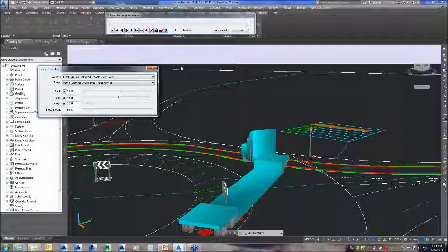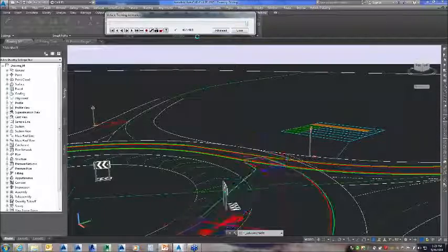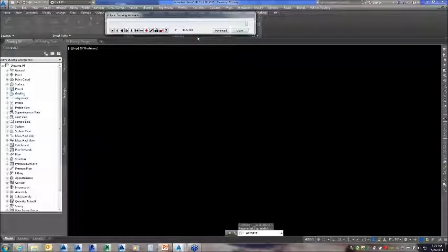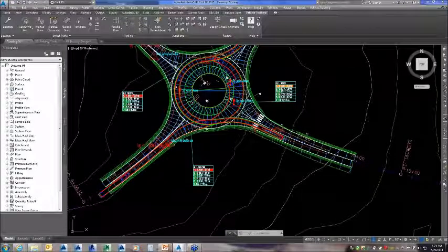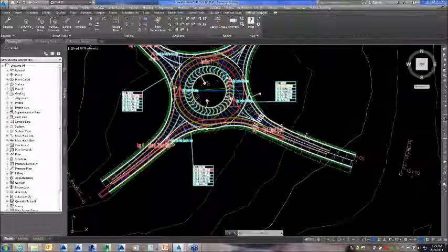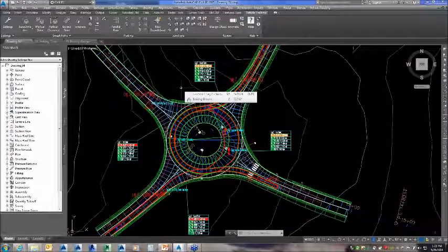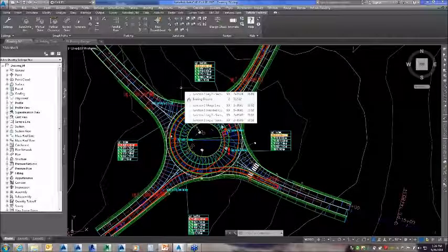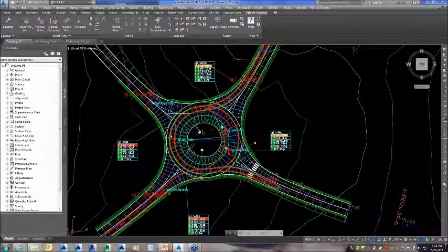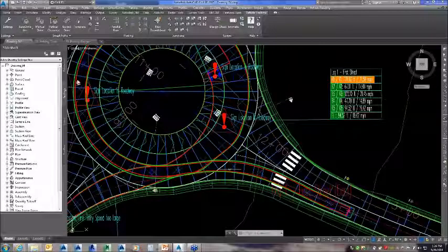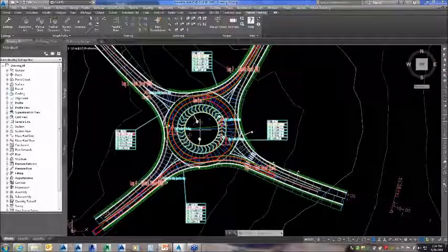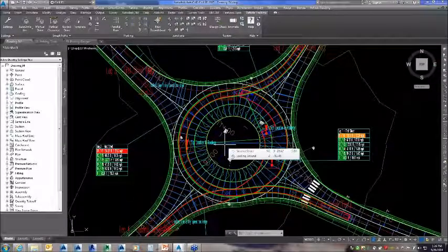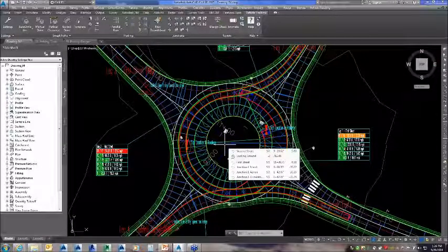Okay, perfect. We have a question from Eric. He's asking, do the AutoCAD objects stay in the file as blocks? Do they need to be purged? No, they stay in the file as blocks. All it is is a 3D block, so specifically if you're making reference to signage or anything, it could be moved to multiple drawings or single drawings. It's just an AutoCAD block.